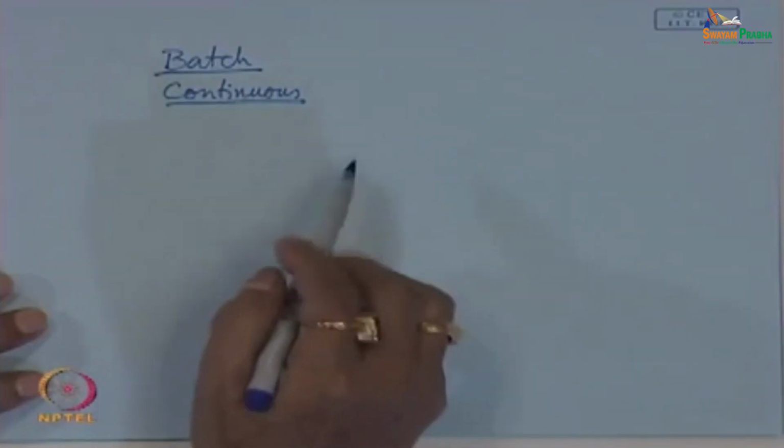But the problem is, in a continuous process one cannot go to higher conversion. Higher conversion is not possible. You can get a high molecular weight product, but the conversion may be 20%, 30%, because there are problems like viscosity and handling of this entire mass.